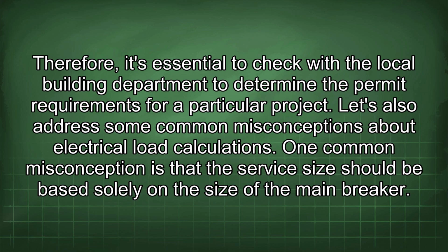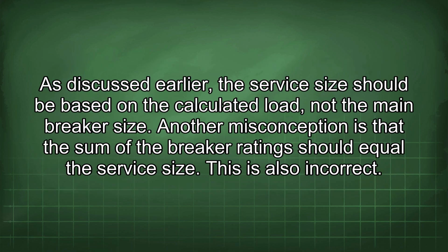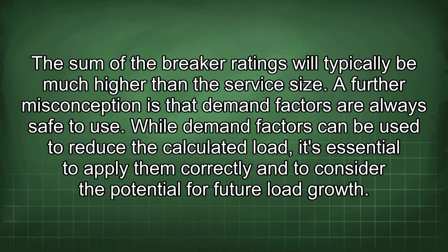Let's also address some common misconceptions about electrical load calculations. One common misconception is that the service size should be based solely on the size of the main breaker. As discussed earlier, the service size should be based on the calculated load, not the main breaker size. Another misconception is that the sum of the breaker ratings should equal the service size. This is also incorrect. The sum of the breaker ratings will typically be much higher than the service size.